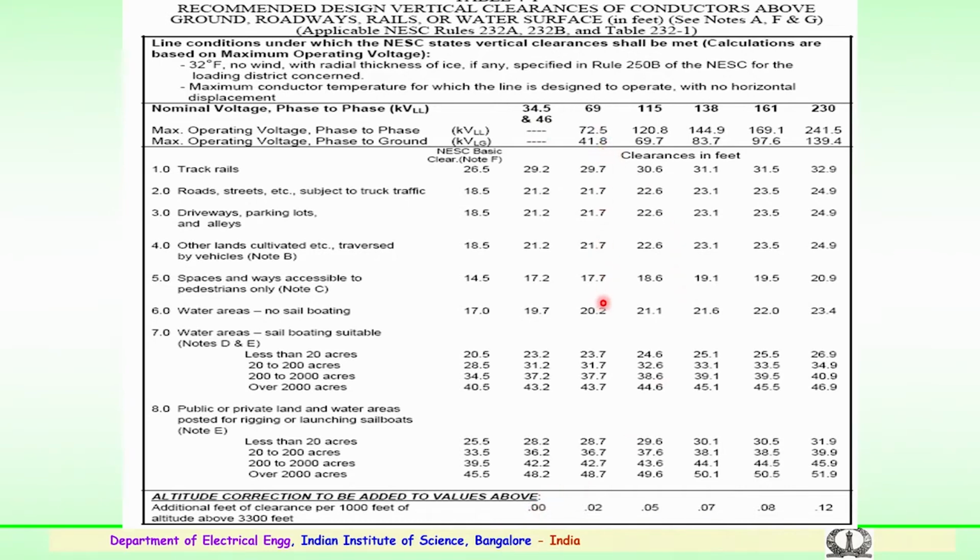These are the minimum clearances which are to be maintained, apart from the electrical clearances to be added to this number. So, for 132 kV, 160 and 230 and so on, the clearances are clearly specified by the National Electrical Code or the Indian Electricity Rules wherever the towers are being erected, either distribution or transmission.